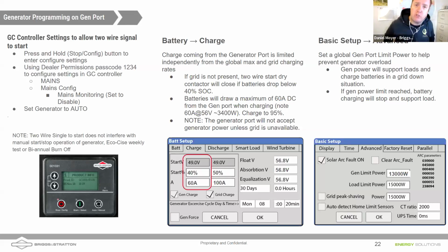Nathan and I are really energy storage experts, but we have a team of generator experts. And I just want to bring up that point here. Andy's asking a great question: how often do you need to do a service call to adjust the valves on a Briggs & Stratton generator? How many hours of runtime? I thought I knew that question, but as we were sitting here, I was able to text and message Andy Renner, who's one of the experts on the generator side. He says every 100 hours of runtime or annually, whichever comes first. And I think Andy's on here too, because he said that it's Tuesday at 2 p.m. for 16 seconds is the exercise.